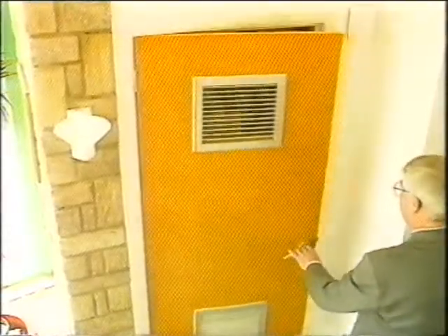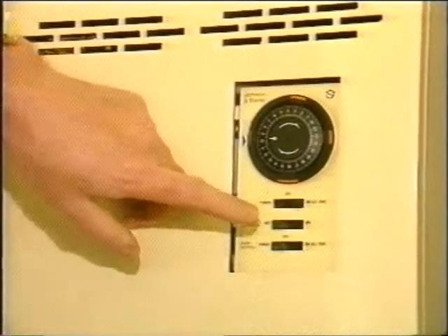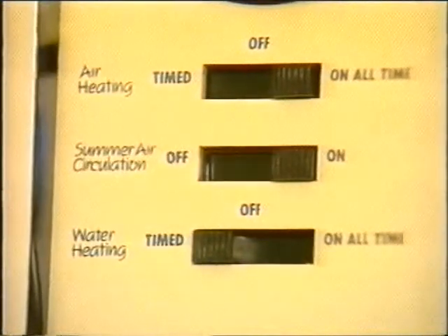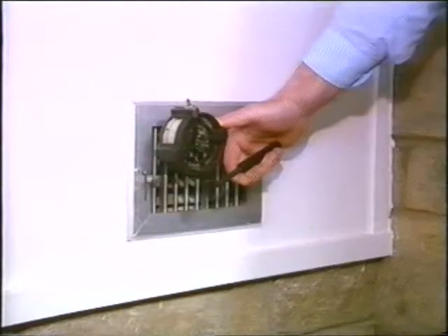When an installation's finished and checked, the main thing to do is balance it. That means using various guide figures to perform a series of calculations which allow you to balance the velocities at each register. Basically, it involves running the fan at maximum with the electricity on and the main burner off. Then partly close the balancing dampers of the registers nearest the heater and open those further away.